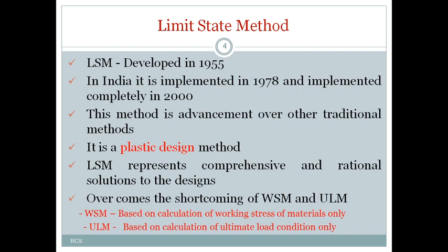Now we are designing the elements of a structure using the limit state method above the elastic limit and below the ultimate limit of a material. That zone is called the plastic zone. So now we are designing the elements of a structure by considering stresses in the plastic region. So the design made by this limit state method may be called a plastic design method. And this limit state method represents a comprehensive and rational solution to the designs.